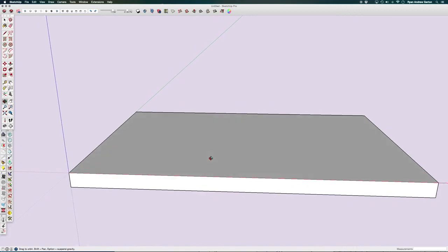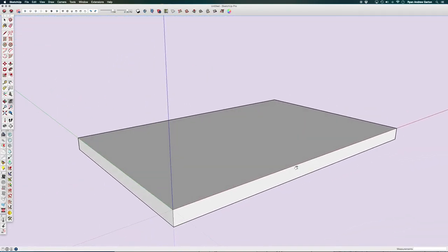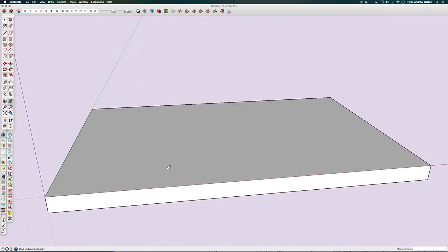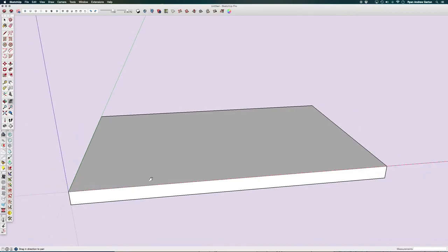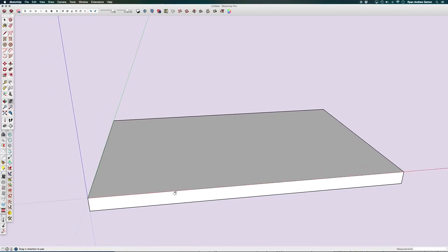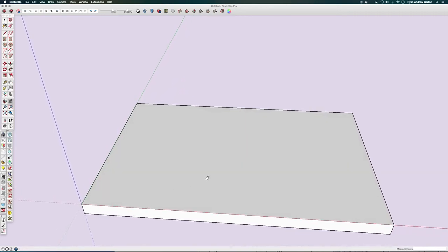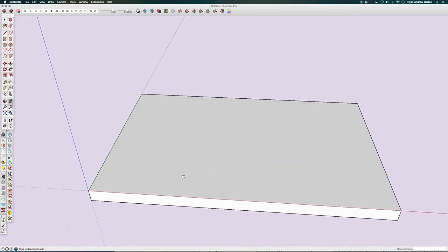We're taking our time away from rectilinear basic push-pull subtraction, and we're going to start looking at how to fuse things together and also cut things apart. So this is to answer your question if you've ever wondered how you do a hole or an opening in a curved wall, or how do you carve something. This is how you do it, and it's called intersect selection.